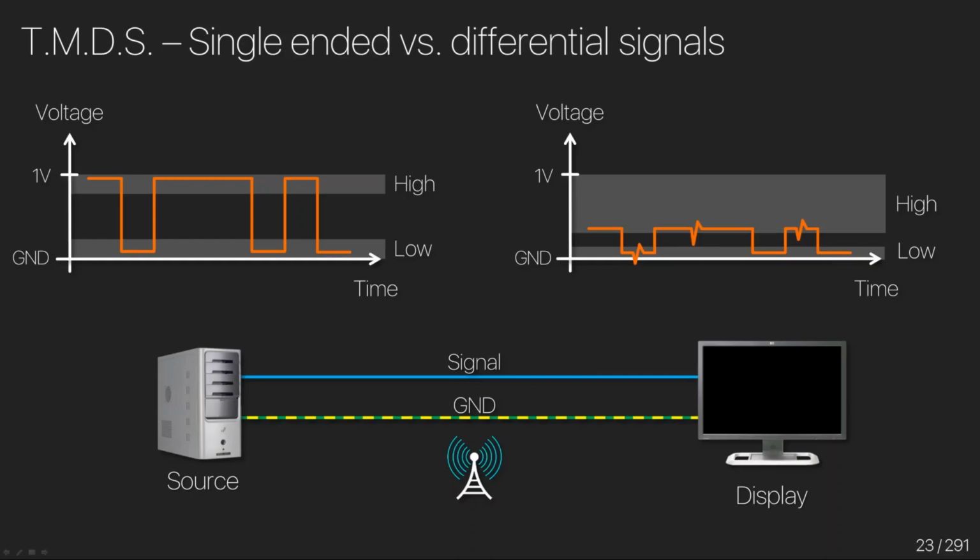And if there wasn't any noise, this would be fine. But unfortunately, there's always noise, which means the voltage is randomly pushed lower or higher, and there are under and overshoots. If you look at this spike, you can see the problem of the single-ended signal. This voltage can either be considered a 0 or a 1, and so that presents the problem. That means we have to use a shorter cable which attenuates the signal less, or eliminate the noise.